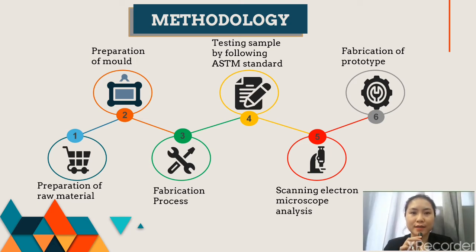The first testing is the thermal test. This testing is to obtain the thermal conductivity of the sample, which is the ability of the sample to conduct heat, and the heat flow of the sample at a maximum temperature of 400 degrees Celsius. The target is to make sure the outer part of the sample is safe to be touched. This testing will use a guarded hot plate method.